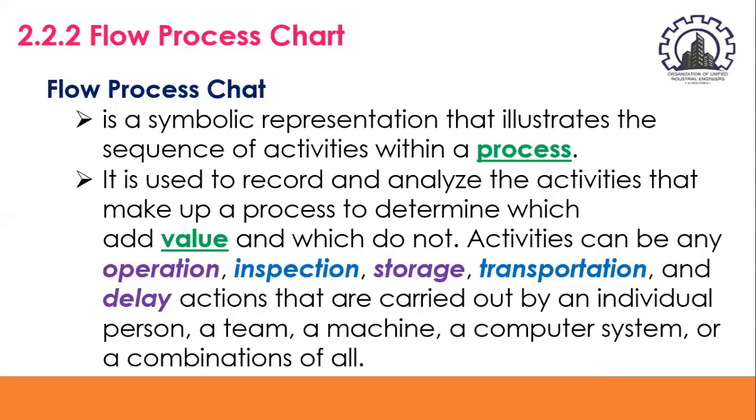Consequently, it is not usually applied to entire assemblies, but rather to each component of an assembly. The flow process chart is especially valuable in recording non-production hidden costs, such as distances traveled by the operators, delays, which may be delays in terms of the operator, the machine, or the material, and temporary storages as well.